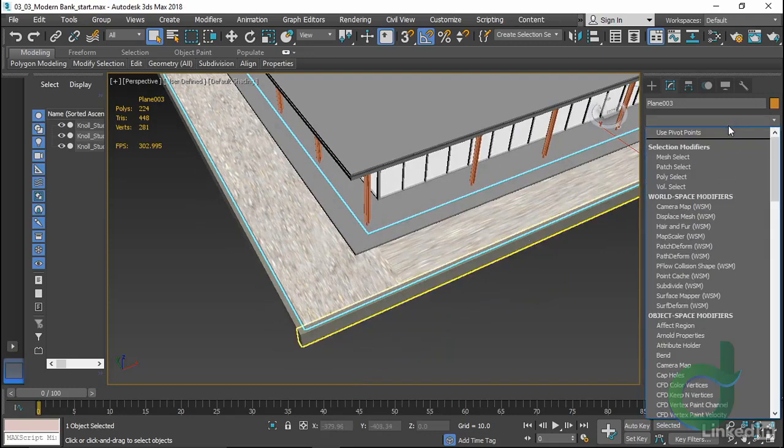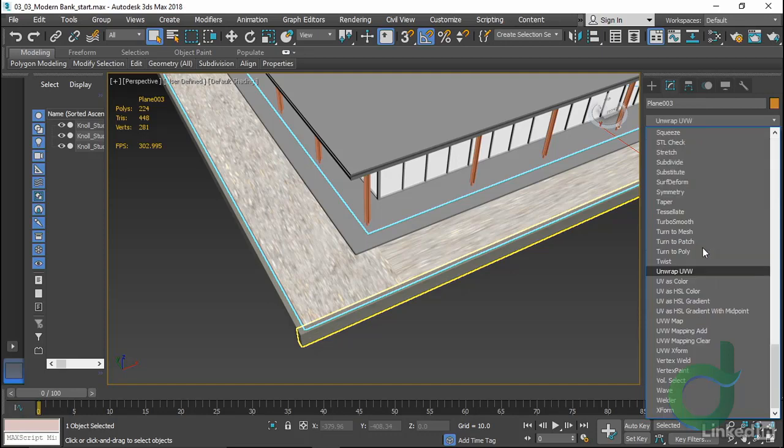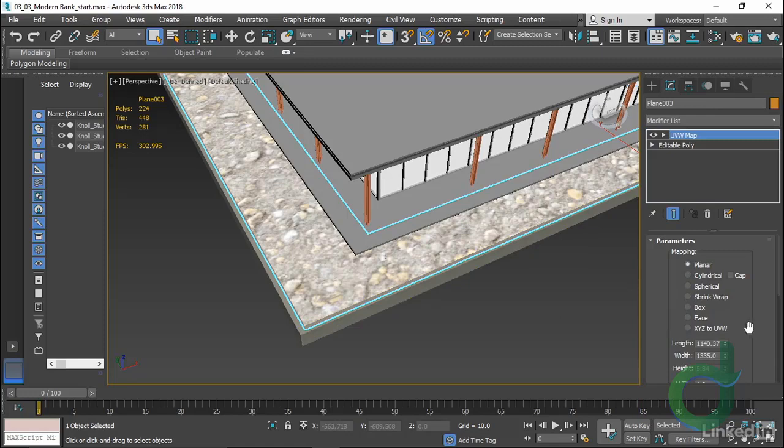Remember that most things coming in from Revit will have square mapping. Most things that you make here in 3ds Max will have default mapping, which you probably will mash by modeling. So we need to adjust them, as we've seen, to do some mapping on it to really get things to flow around. I'll put a UVW map modifier on, and in this I'll shrink down the size.